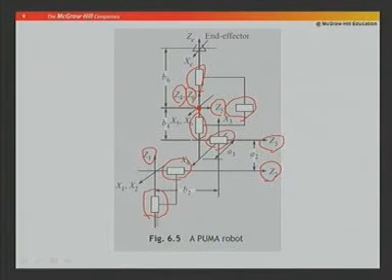Okay. Now, after that I have applied the DH formulas to set other axes. So, common perpendicular of Z1 and Z2 should be my x2. So, I have drawn x2 here as a common perpendicular.